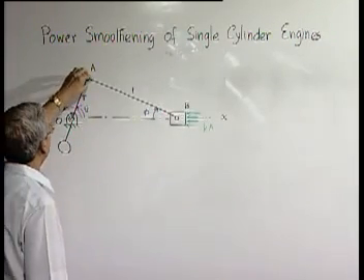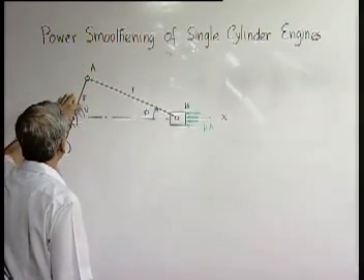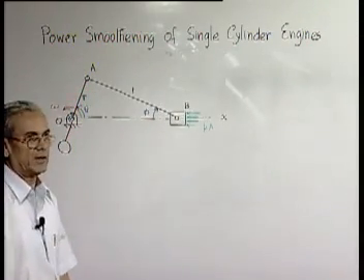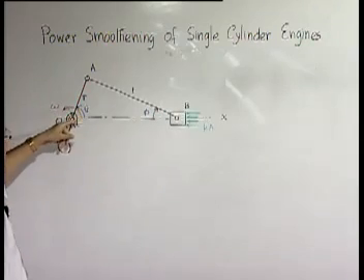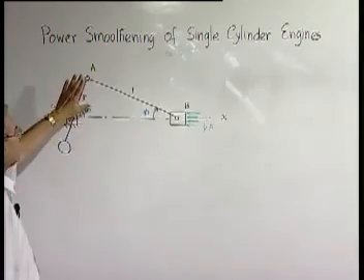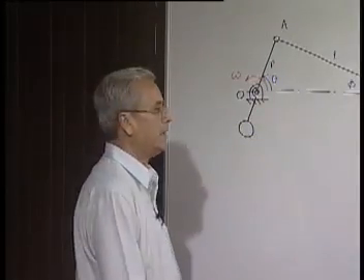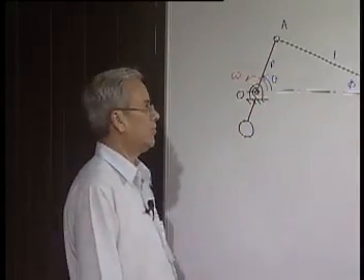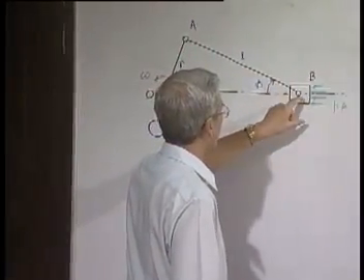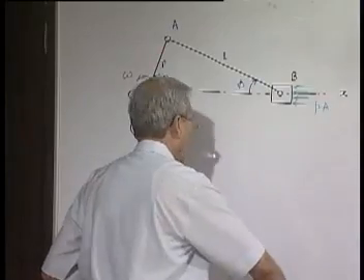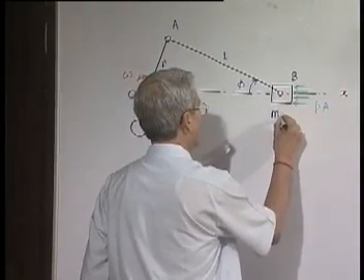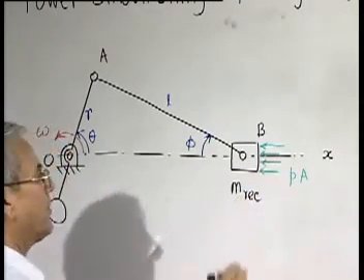And we have seen that this mass, the crank's original mass, all these are actually purely rotating objects. And therefore, to balance that, we always generally put a balancing mass. But really it does not play any role in this analysis which we will be doing. On the other hand, the other apportioned mass which goes here, that along with the mass of the piston etc. in total becomes the reciprocating mass, that we have seen.